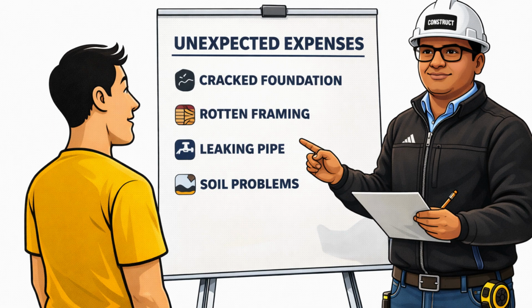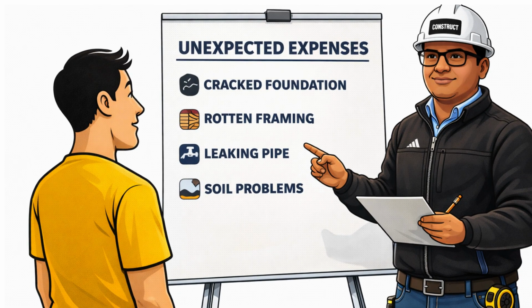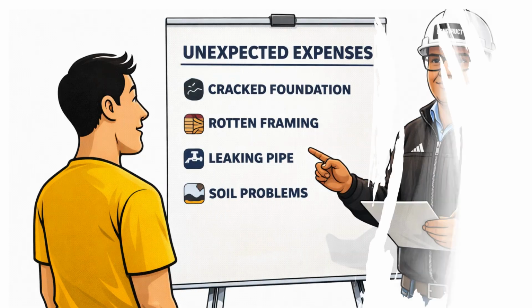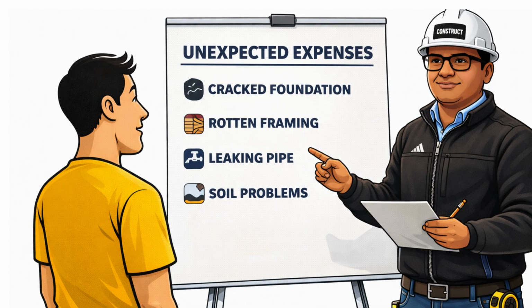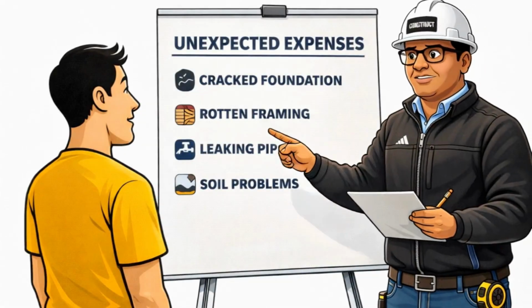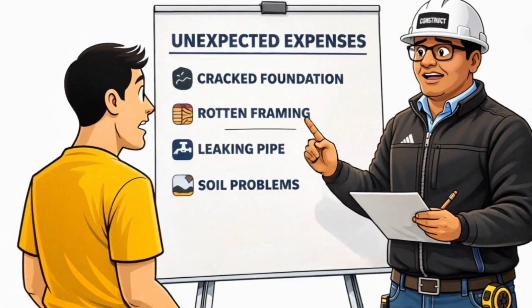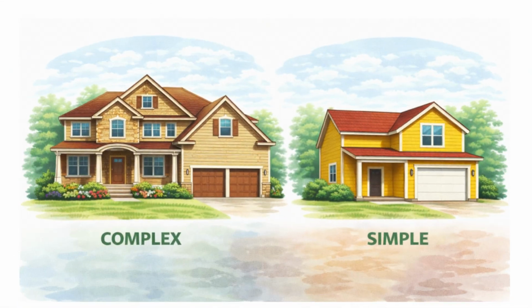Fixed costs appear even in small houses. Site setup, permits, mobilization, basic foundation preparation, basic supervision. Variable costs scale with size. Cement volume, block work, plaster, paint, wiring length, tile area. But multiplier costs are different. One small design decision triggers more structure, more labor, more detailing, more risk, more delay. Now let's talk about the first multiplier.